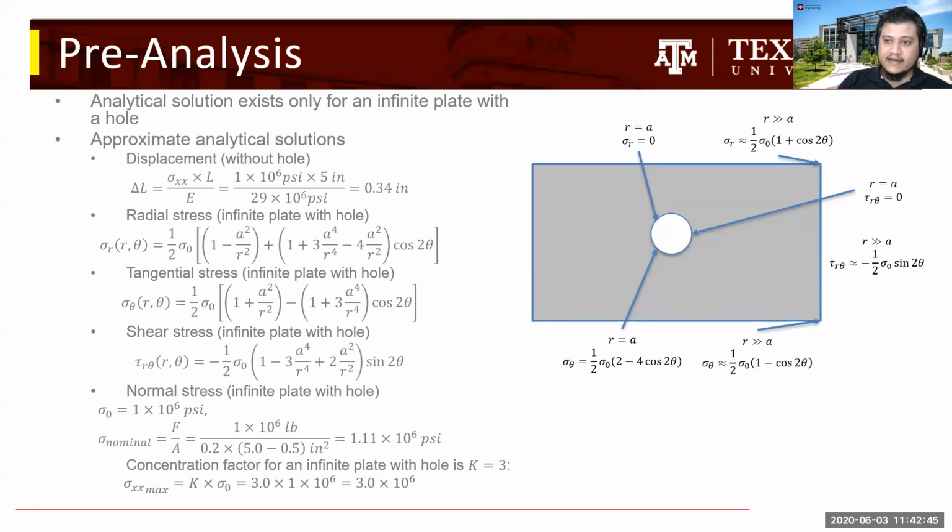This is a sanity check, and it is required to see whether we are not making any major mistake while setting up our problem or our physics. So pre-analysis is almost always necessary in any FE analysis, or for that matter any simulation, so that you back your results with some analytical relationships to establish sanity.